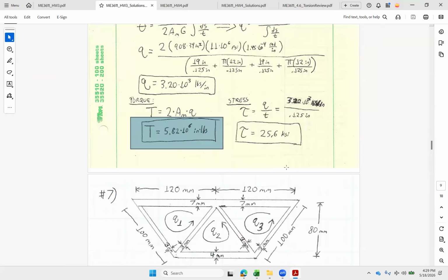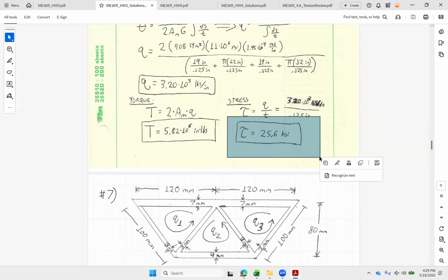So let's see. That all turned out pretty poorly. Oh, so the punchline I was going to get to, the company that designed the original one is the one that they hired to redesign it. And they put it in another flat oval with even more stiffeners, and then it cracked more. And then finally they went back and thought about doing a round, which is pretty standard for modifications and repairs. Anybody have any questions about that?